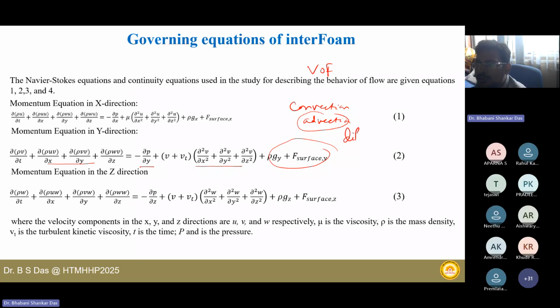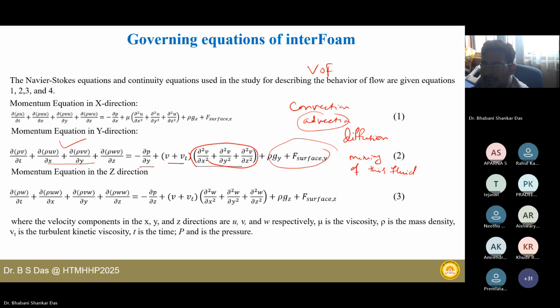And there is another term you used to hear in the equation, that is diffusion. This is nothing but the diffusion form. The shear stress and the eddy viscosity are the diffusion terms. Diffusion means the mixing of this pollutant with the fluids, how the mixing is occurring. This is generally denoted by second order equations. So first order equations are generally convective, in a space-wise manner. Advection is when there are some pollutants or sediments, and diffusion means the mixing process.